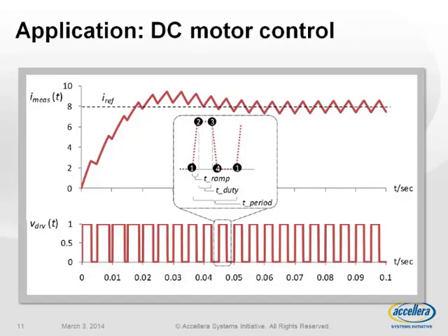An application example for these new features can be, for example, the DC motor control using PWM modulator. If you would try to model this with SystemC AMS 1.0, you would need to specify a very, very small time step to have the right resolution to capture all the different widths of your pulse. And if you then would look in your system, you would basically do nothing because the signal itself stays more or less constant over this time.